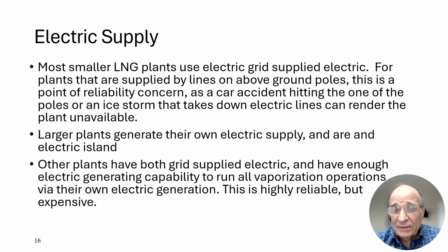One of the things that's interesting is if you do have your own electric supply, I often ask the operator, have you ever tried operating the plant at maximum requirement using solely your electric generation capability? And quite often the answer I hear is no. So if you do have your own electric supply, I do recommend driving the plant to full capacity using that electric supply to see if everything performs the way it is designed to perform.